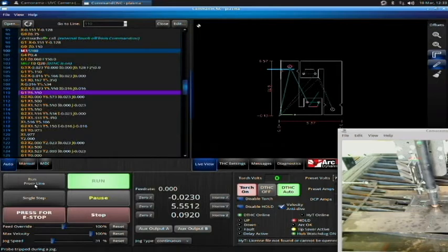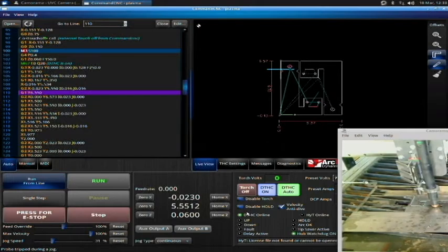So this next error is very similar to the last one. You might be asking, why did my machine stop in the middle of the cut? Well, in this particular case, it stopped because the air pressure went too low. One of my coworkers turned off the compressor, and so we ran out of air. Okay, so as that compressor charges the system back up, the first thing I want to do in this situation is, same as before, hit the stop button. That turns off the torch, and it pulls it out of run mode.